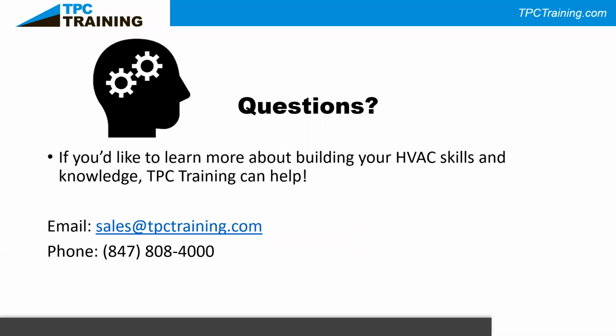What do you add? What don't you add? One of the things we could have talked about, and maybe we'll consider adding for another class if this takes off, is what we do offer in our virtual reality: psychrometrics, the measurement of moisture in the air. So Ryan, if you're in a 70-degree room and it is low humidity, 30 percent, you might feel comfortable. But in that same 70-degree room, if we're not getting humidity out and it's pushing above 50% humidity, you're not going to feel as comfortable.